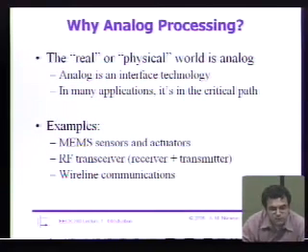Yeah, DC-DC converters. Even if you're building digital circuits, they need to be powered up from a battery. And you don't simply connect the battery to the IC. There's actually lots of circuits that go between the battery and the IC, not only to change the voltage, but also to be able to supply the right amount of current, to minimize the ripple on the supply, to be able to handle a varying load. So designing DC-DC converters is actually a big area of analog circuits.